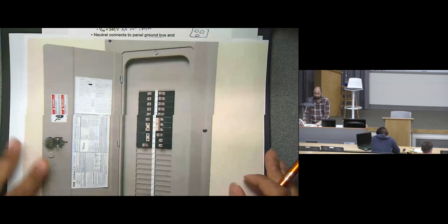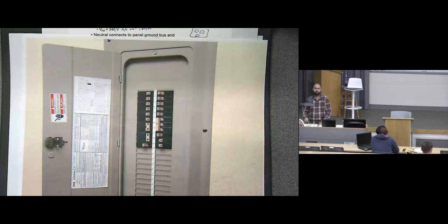So what's the circuit breaker and why are we using it? A circuit breaker is basically for connecting and disconnecting the circuits. Why are we using it? The circuit breaker is for protection. And when we are doing some kind of maintenance, we trip the circuit breaker, disconnect all of the power from your home, do your maintenance, then reconnect your home. This is not only that, it is also for protection. If there's something wrong in your system, the circuit breaker should deal with it.